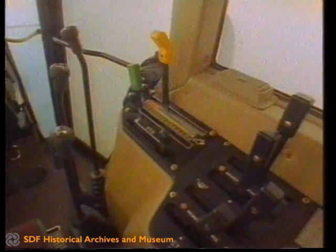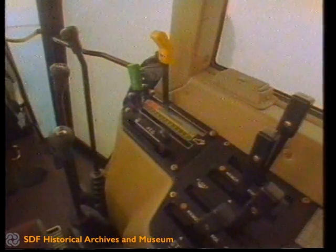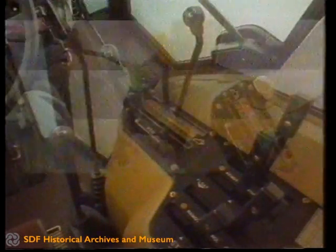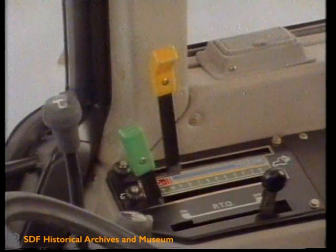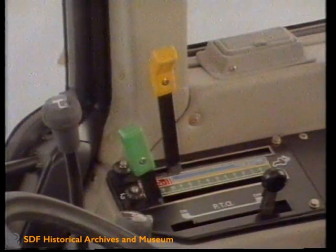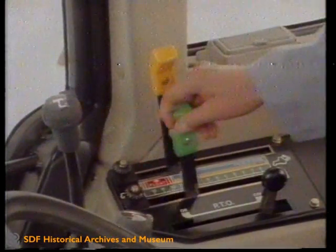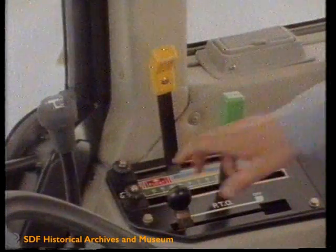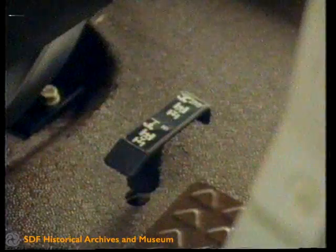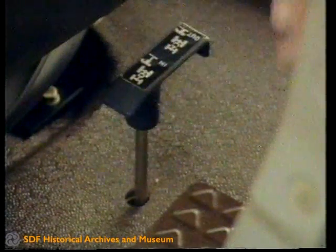The layout of the controls has been designed according to improved ergonomic research. All levers have been positioned beside the driver, thus giving a completely free driving position. They have been arranged so that those in most frequent use are on the right-hand side: gear levers, hydraulic lift and auxiliary hydraulic levers, PTO control, whilst those which are less used are on the left: four-wheel drive engagement lever, parking brake, synchronized PTO engagement.